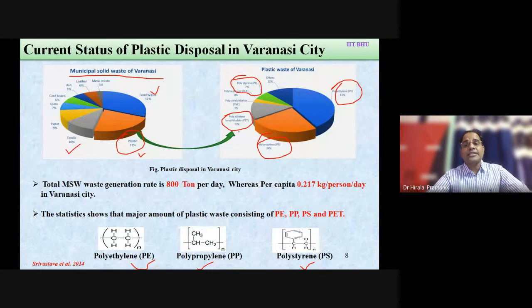But PET is not considered because it creates a problem of benzoic acid when it is broken down by thermal pyrolysis. Benzoic acid is a byproduct which basically chokes the condenser and creates major problems in collecting the products. So that's why it is not recommended to do pyrolysis to get fuel-like hydrocarbons. Polypropylene, polystyrene, and polyethylene could therefore be considered a good source of energy material to get fuel-like hydrocarbons.